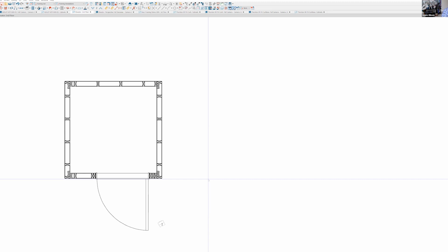But there's a few little tricks that are very helpful when doing this, to cut down on the time and the labor that it would take in the future, if it ever gets done. So typical floor plan here, I hopefully find out which kind of elevator might go in there. Usually you need some solid rails here for the elevator rails to attach to. So you put those in as just 2x12 fills.